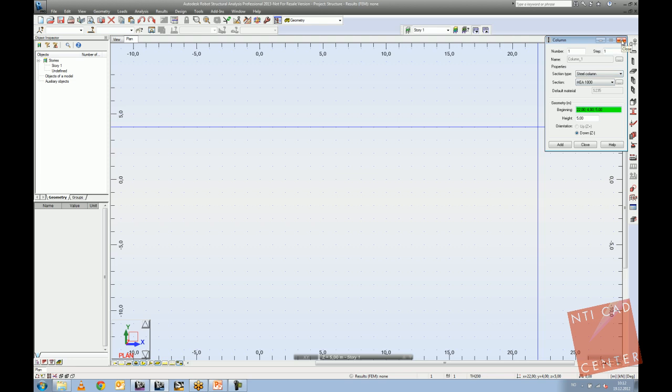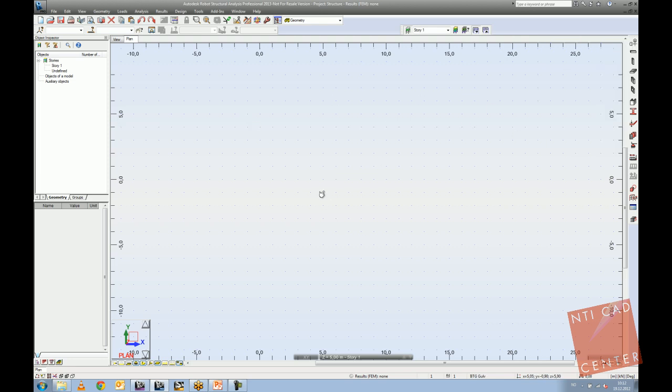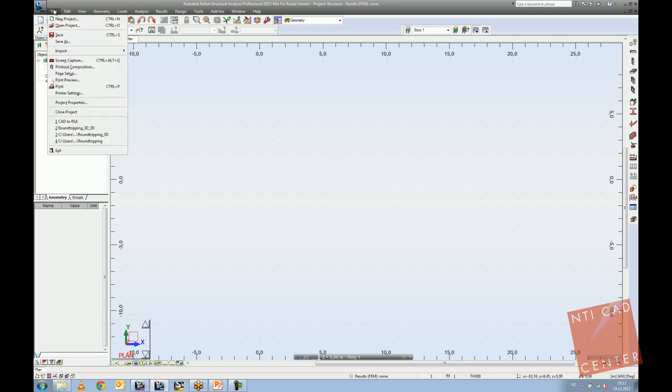Again, you can start modeling from scratch here, which is what most people do, but you can also utilize the data you have. So, taking AutoCAD files: in most cases when you start analysis, you'll already have a structure defined. If I go to File and Import, you will see an option called DXF and DWG backgrounds. That's basically XREF in AutoCAD, I can call it that way.